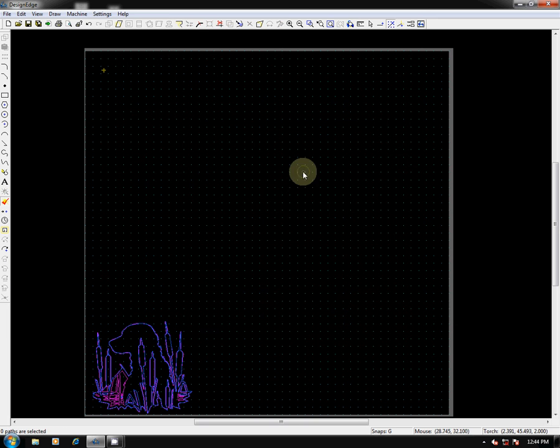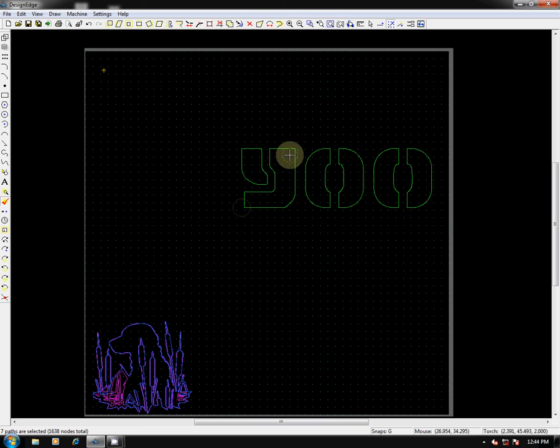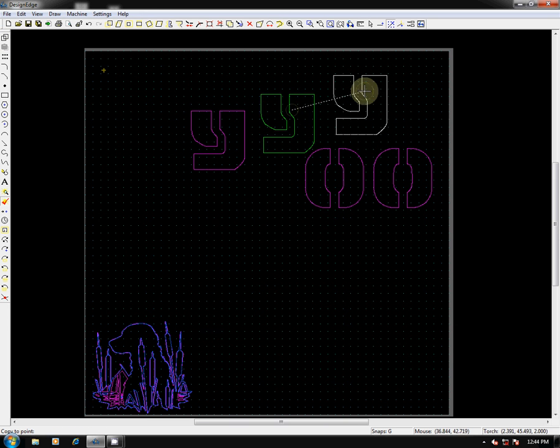And that's it. You can import letters like I just showed you. If we wanted to, we can highlight it and use these tools up here, these boxes. If you hover over them, it should tell you what it is. Sometimes it won't though. This first one is move, so you can click it, move your part. There's one over here in the left, which is copy. So if you wanted to get crazy. Okay, so if I wanted to say that one and control click to that one, and then up here is combine. So you see that? It kind of took away those lines there and combined those two shapes.